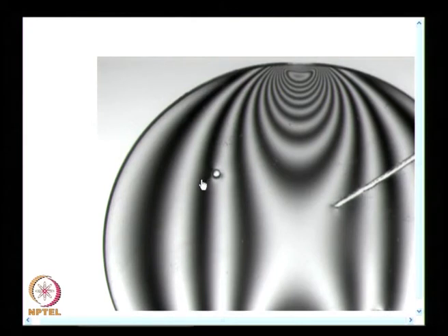When you see it in color, you will see the color change. In black and white, you will not see that change. You will see that this is as good as the slot that you have made, and that is the reason why I showed the fringe pattern in color. Color variation, we have also seen, has been used for calibrating the polariscope and for finding out the sign of the boundary stresses. Wherever you come across small variation in fringe orders, color sequence is the best way to look at.